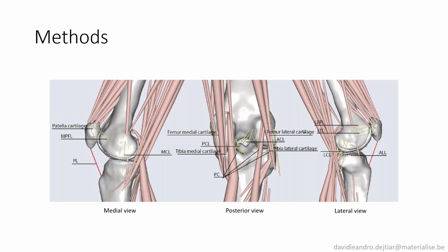In here, the ligaments were modeled as non-linear elastic elements between the attachment points previously selected. The contact forces were based on an elastic foundation contact model, and the muscles, whose attachment points were selected during the morphing process, were modeled as three-element Hill-type string muscles wrapping over the bone surface. A third-order polynomial cost function was used to minimize the cubed muscle activations in order to solve the muscle recruitment problem.